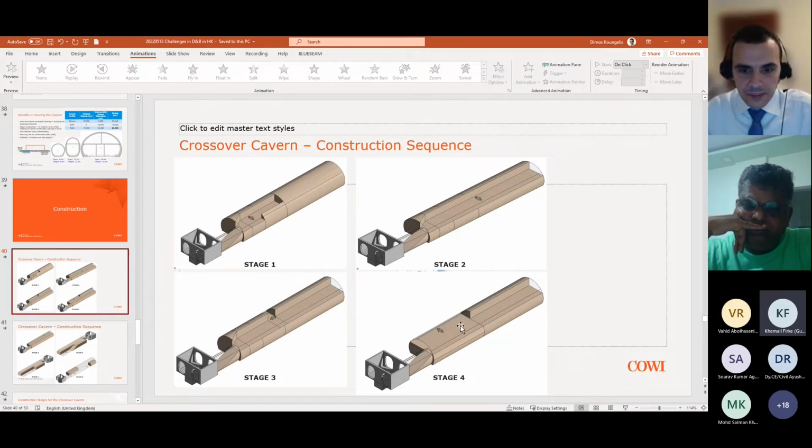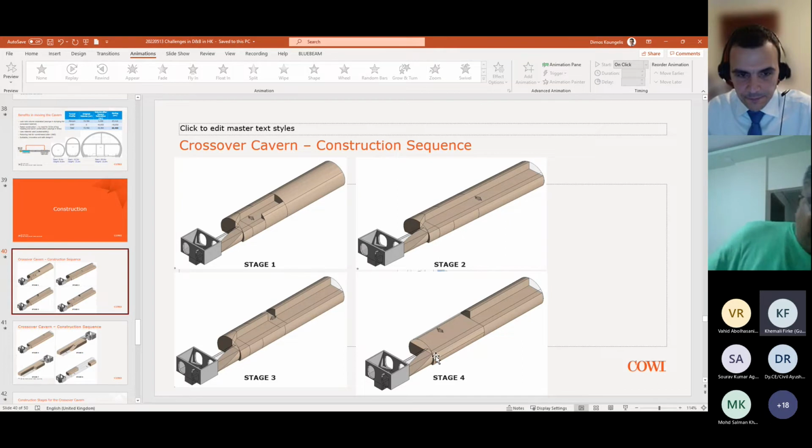So what we try to do is to see what the support requirements are for the big span, for the whole span, and we try to install that even when we were excavating the smaller phase. So we would install the support that our analysis and our assessment would indicate that we need to install when you excavate the full profile. Okay, thank you very much.